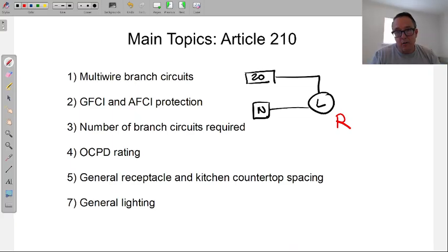This is why the hot and the neutral that both go to the light bulb don't have a short circuit yet. If I got rid of the load and bypassed it in some way, now I've shortened the route of the circuit. This is why they call it a short circuit. Basically, what happens in a short circuit is resistance drops to 0, amperage, inversely proportional, skyrockets, and some crazy numbers start to apply, like 10,000, 20,000, 30,000 amps going into this basic 20 amp circuit.